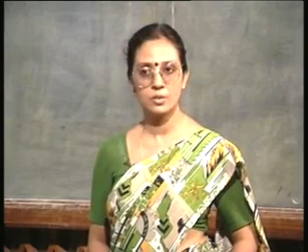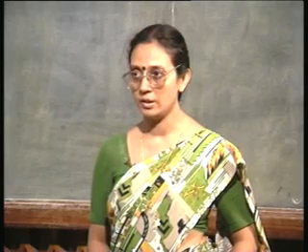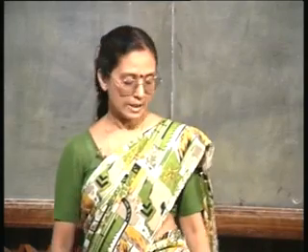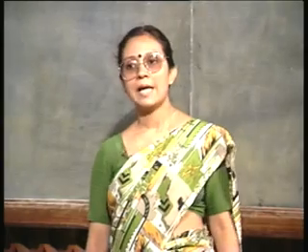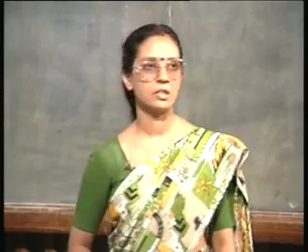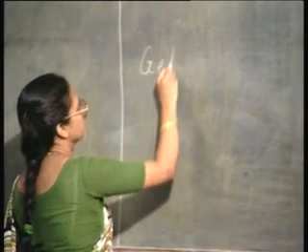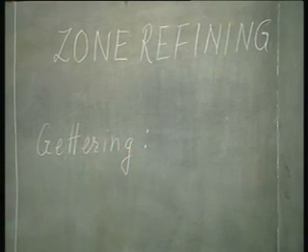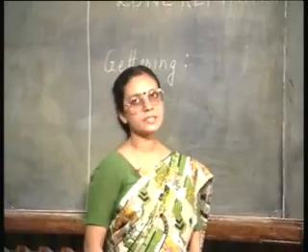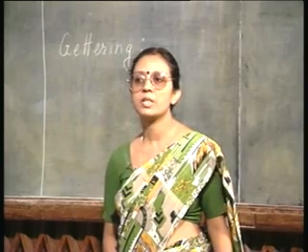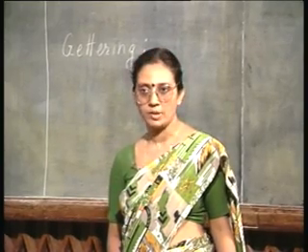So, the crystal thus grown, we call it the bulk material. It is grown by the crystal growth technique and we have the bulk material. Now, this bulk material can then be subjected to some gettering processes. This gettering is done so that the active region of the device is free of any metallic contamination.